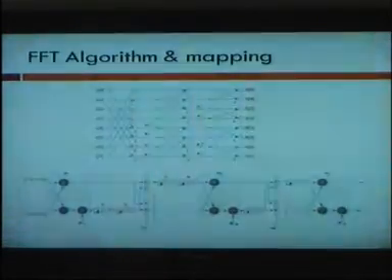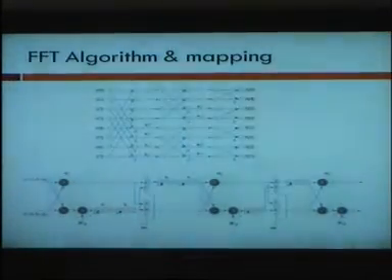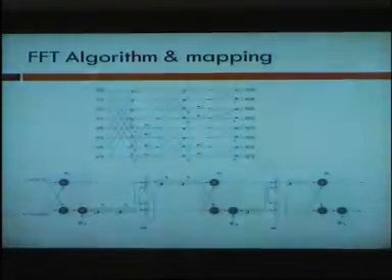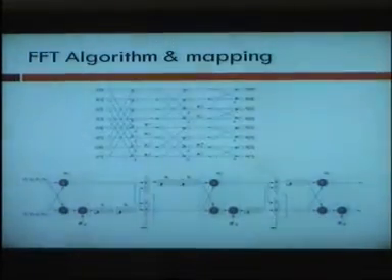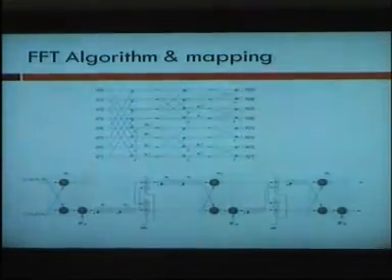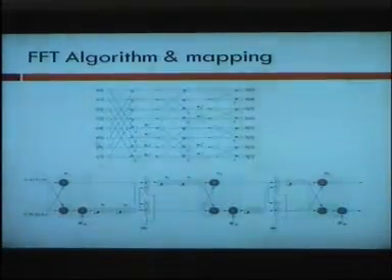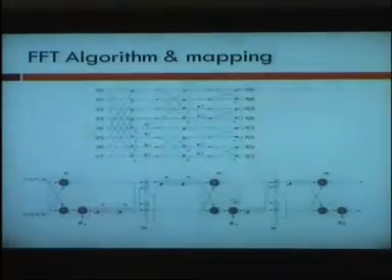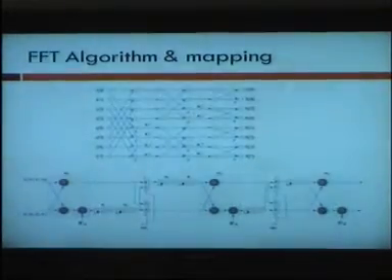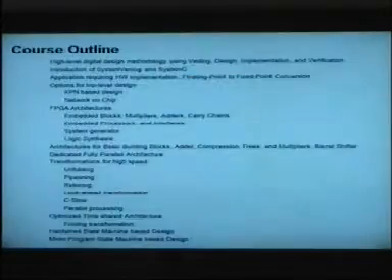If you ask somebody to design, usually this will be their first preference because it's very easy to design, but disastrous as far as the area or the resources are concerned, because mostly you don't need your algorithm to work in parallel. You don't need to do everything in parallel because you don't have those types of requirements. So it's very rare that you need to do things like this. Mostly you need to come up with a creative way of doing things, where you are minimizing your resources and just getting to the required throughput, whatever is required by your application.